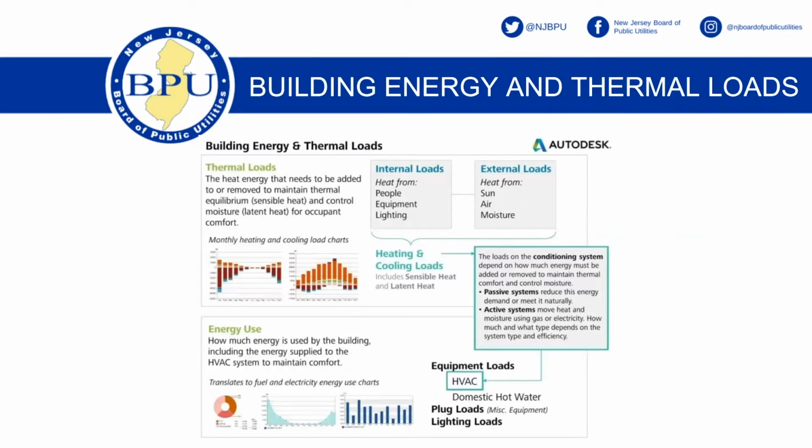Regulating ventilation appropriately can save a tremendous amount. I've seen situations where we were doing 12 or 13 air changes per hour on a 24/7 basis, if you can imagine. This is in a 500,000 square foot building. So what that means is if it's 12 air changes an hour, that literally means every 5 minutes, you're opening up every window in the whole place and you're blowing all the cold air out of the building or hot air out of the building and then making up for it again. It was a complete energy hog.